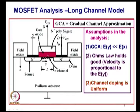So, this is the diagram which you will see everywhere in textbooks, all textbooks. You can see that you have got the substrate which is made up of silicon in the conventional MOSFET, and you have got the red color is the oxide, then this is the polysilicon gate. If it is an N channel MOSFET, it is N plus heavily doped, and you have got the source drain, N plus source, N plus drain.